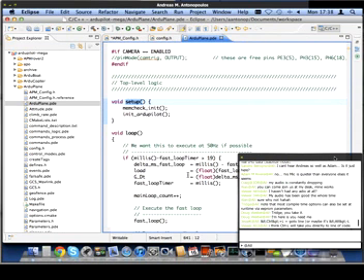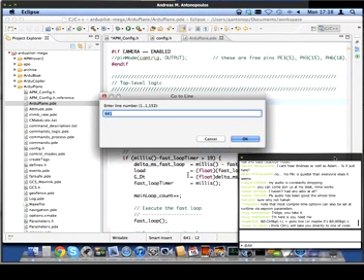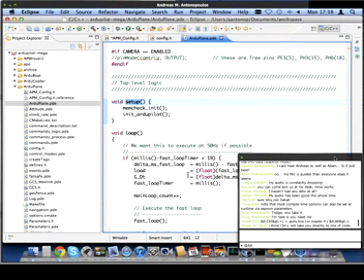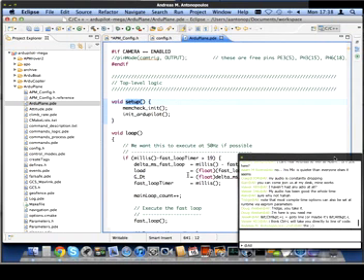One is the memCheckerInit. That sets up a little memory checker that we use. We had some problems in the past with running out of memory on the APM. The APM board only has 8 kilobytes of RAM, and it's very easy to run out of that amount of memory. And so we had some issues. We were getting down to our last few bytes, and so we added a new system called memcheck that provides runtime checking of the amount of memory we have left.